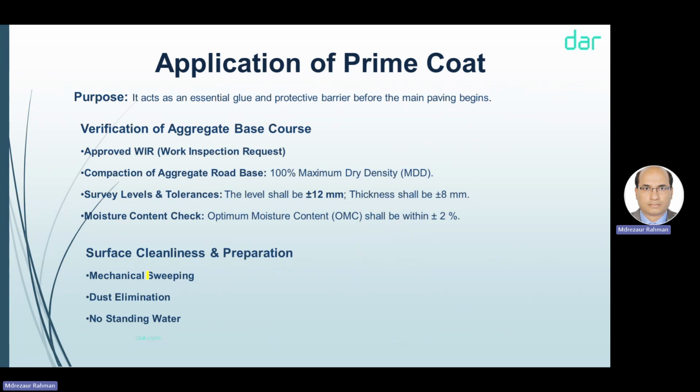We are looking at the thickness tolerance. You can follow plus minus 1 centimeter for our project, but at ADQCC it is 12 mm. So 1 centimeter is within the limit.